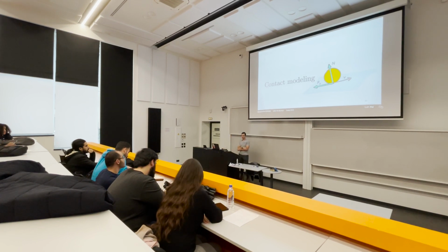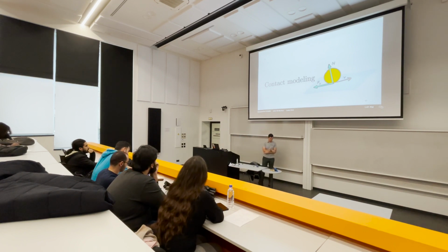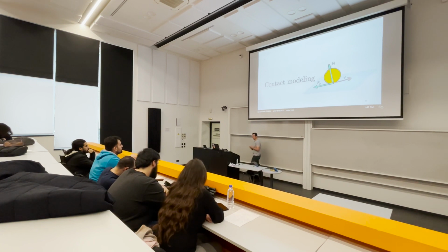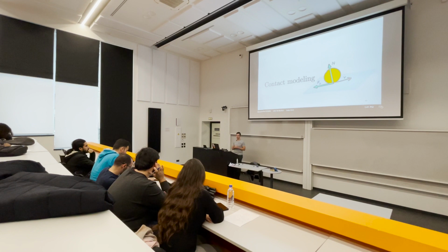If you do modeling in different kinds of simulation packages, for example, free open source projects, you can use Python with different simulators such as Bullet or Chrono or MuJoCo, and you will have a lot of different ways to model contact. But we're not going to cover all of them. We will cover just one of them, which is called penalty-based.